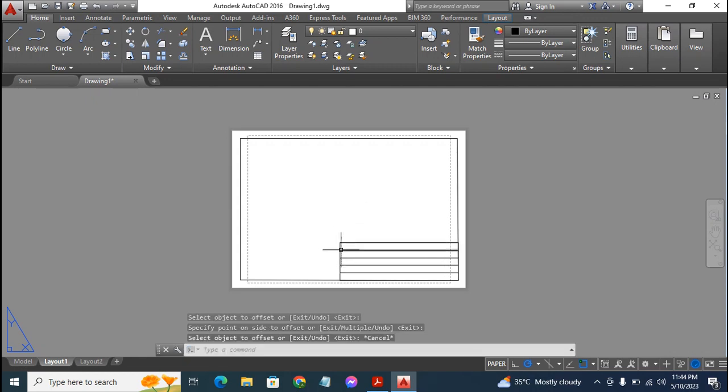Next up, we want to start offsetting the vertical. So I'll get rid of this horizontal line I drew in there. It has served its purpose. Press delete to get rid of it. So next up, I need to offset this vertical line here, the width of the rectangle. Let's offset at a distance of 40 millimeters. You try to get the actual or the recommended size from your institution, whatever school you are attending. I believe there are standard sizes for title blocks. So you try to get the actual size. I'm just using these sizes for the purpose of this tutorial.